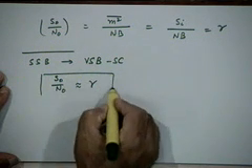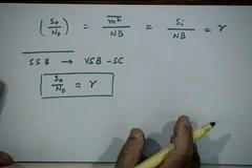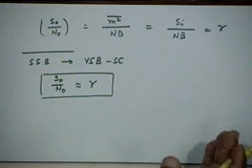So whether it is DSBSC, whether it is SSB, whether it is VSB, the performance of the system after synchronous demodulation is the same, right? Same as that of the baseband system. So really you are not achieving anything in terms of SNR performance when you are doing amplitude modulation. That's the message. That's the moral of the story. Okay, that's what you need to understand.